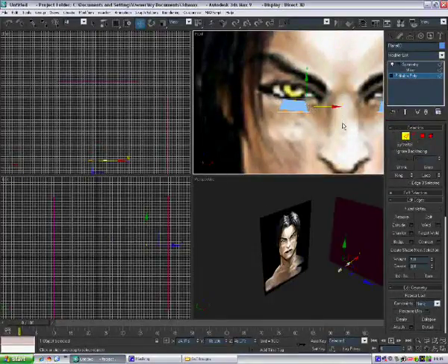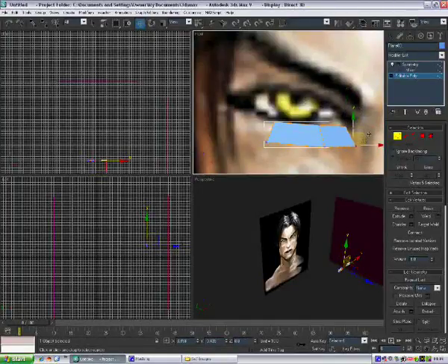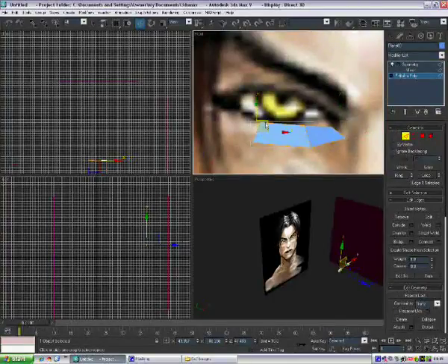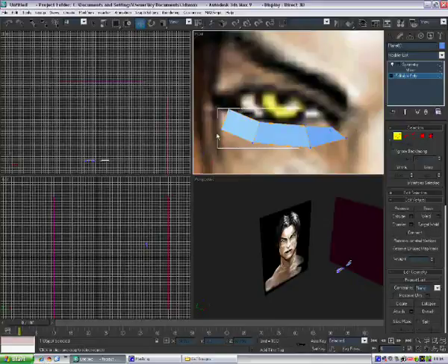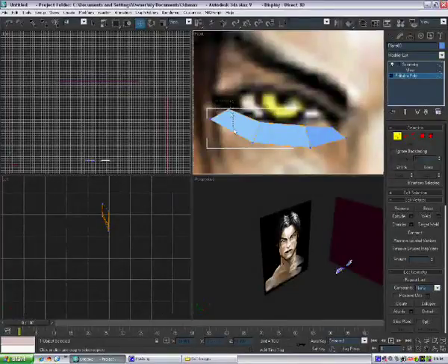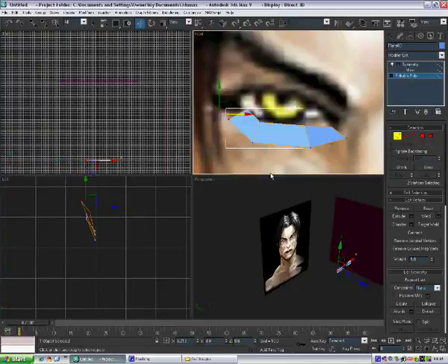It's not actually that many skills apart from rearranging vertexes, and there we select an edge and move with the shift key held down to create another face to rearrange. You can select multiple edges and drag with the shift key to create multiple faces. That's the main skill that we'll be using in this tutorial, and of course we'll be using bridge and weld tools as well, but apart from that, that's about it. So match this in all the different viewports.